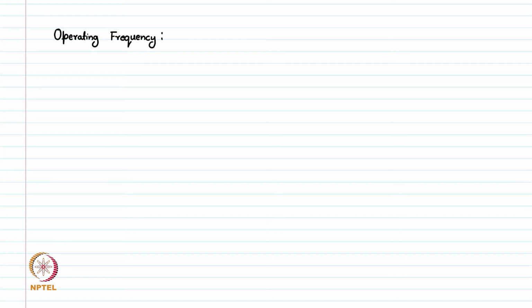Operating frequency is the first parameter which is decided before starting the RF PCB design, and the RF PCB layout approach through which we are going to design this RF PCB varies tremendously across the frequency spectrum. For example, for lower frequency PCBs we have a different approach of RF PCB design, but for high frequency RF PCBs we have an entirely different approach for PCB design.